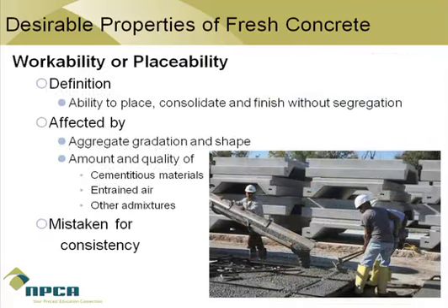Workability, also referred to as placeability, describes the amount of effort it takes to place concrete in the form, consolidate the concrete, and then finish the concrete while avoiding segregation. For those of you not familiar with the term segregation, it refers to coarse aggregates sinking while the fine aggregates and cement paste float to the top of the form. When this occurs, the concrete mix is no longer consistent or homogeneous. Therefore, segregation is highly undesirable.